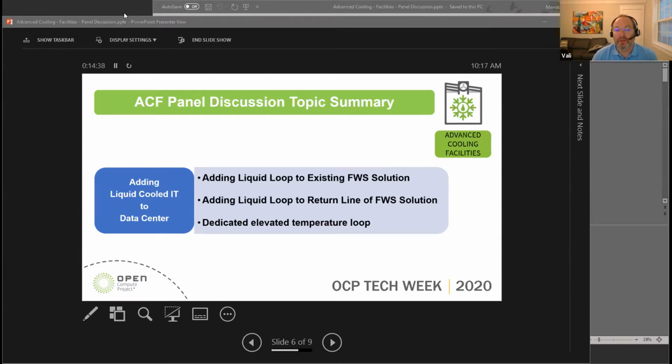Eliminating any central plant or chiller plant is a good thing, because not only do you remove the energy associated with operating large chillers, you are also taking away certain issues like dew point control, it becomes a non-issue. And it makes complete sense to operate at a high temperature so that you can take care of all the HPC equipment. But like I said, Goldilocks zone.